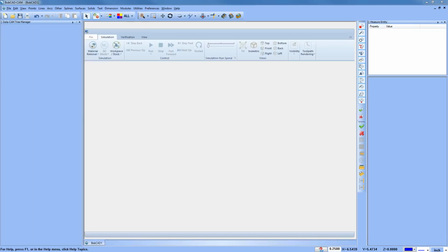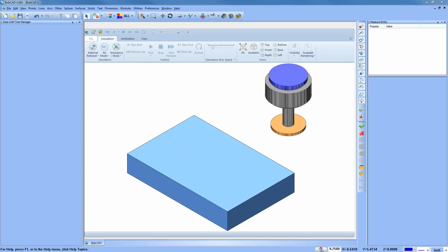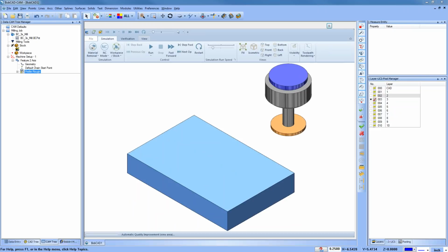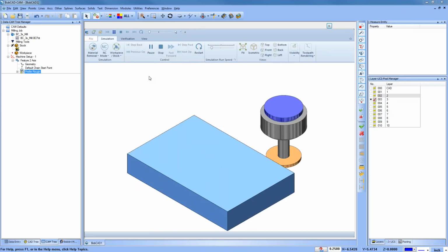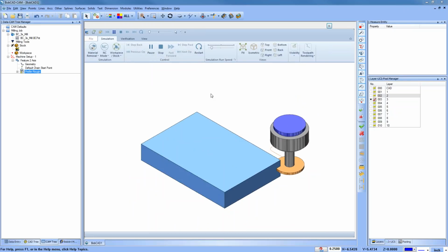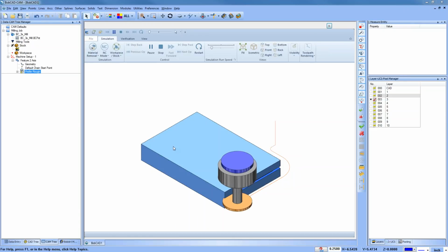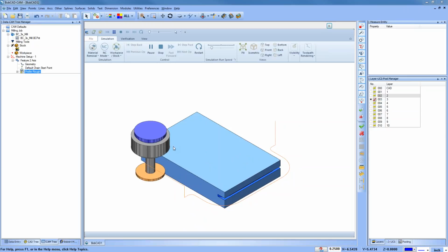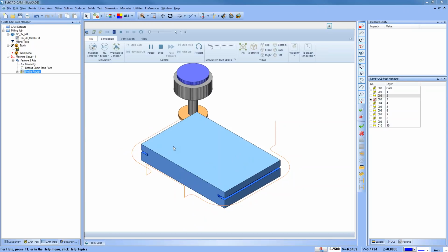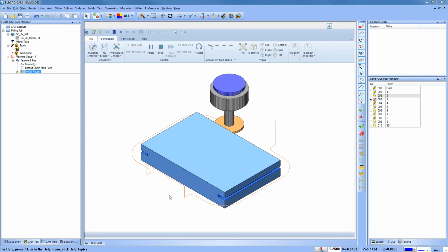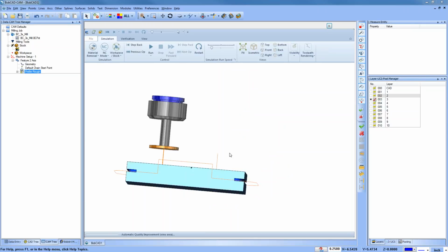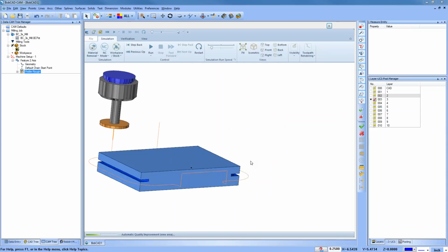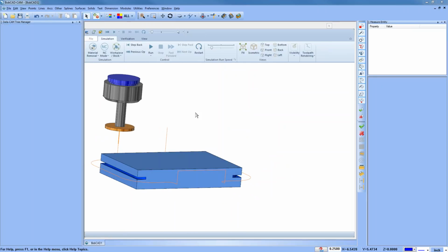You may need to do an undercut. It could be like an O-ring groove. It could be some kind of just relief. It could be part of the part marking here. It could be an aesthetic feature. But in this case, we're using a T cutter to come in. Again, with our profile, we're just using a different style tool. And we're able to come in and do this undercut here. All right. So using your standard profile with a different style cutter, you could come in and do an undercut.